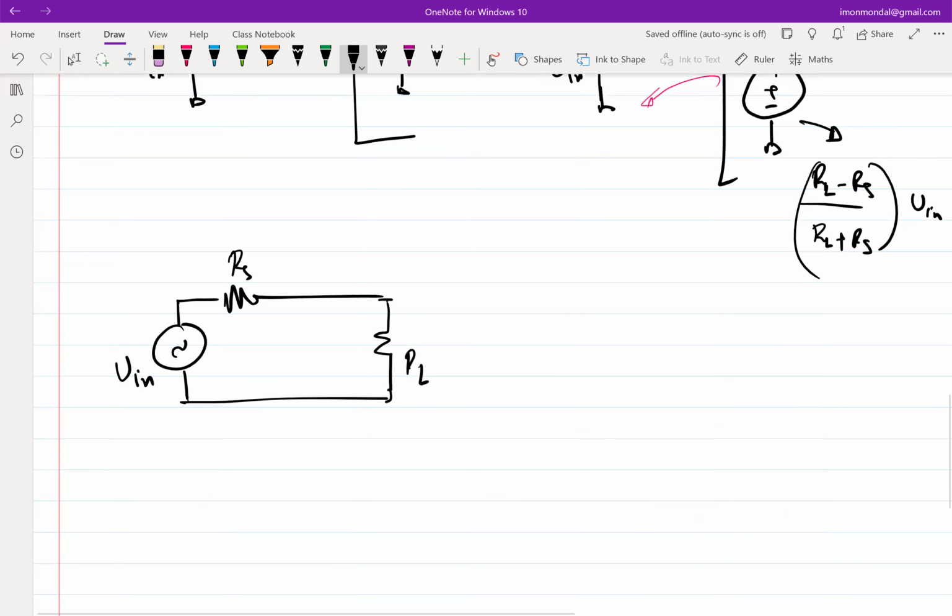So if I have a reference plane here, what will the voltage be then? P in is under matched condition. So what is the forward going wave? P in by 2, right? So whatever the waveform is under matched condition should be the forward going wave.